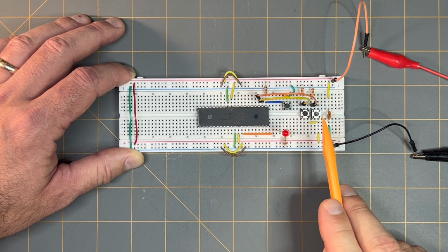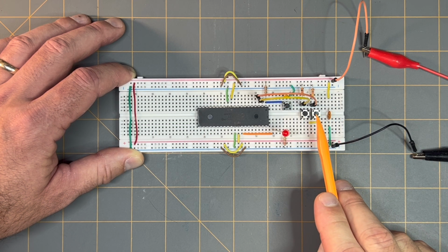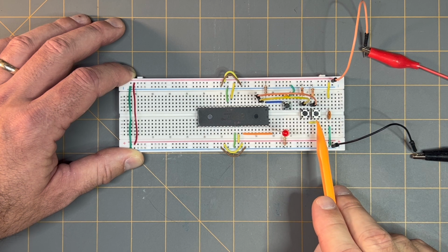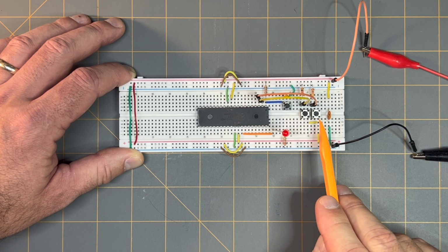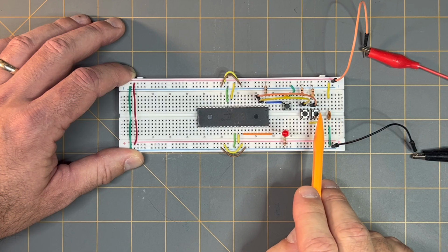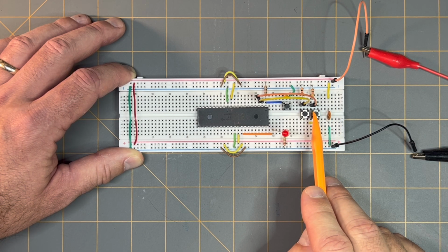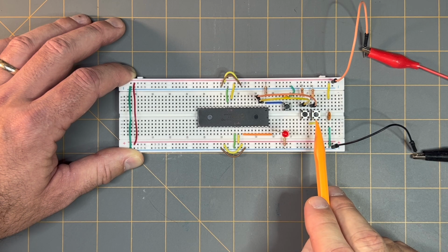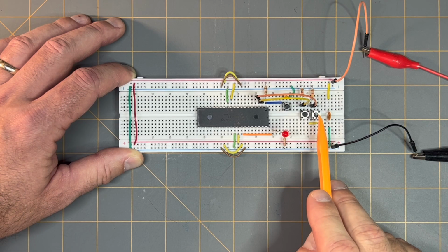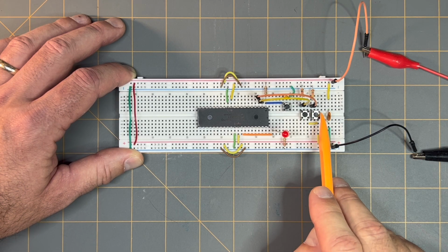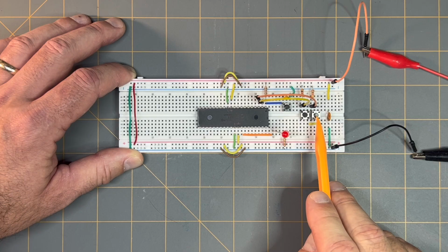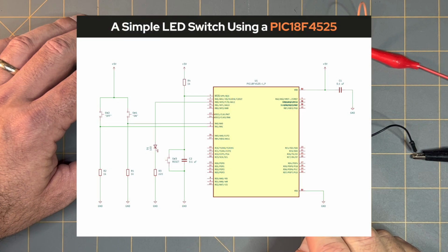And then next I took the second momentary switch and placed one side of its terminals onto points E7 and E9, and the opposite terminals are at points F7 and F9. And again, both these sides are isolated from each other. And this is switch 2 as referenced on the schematic diagram.